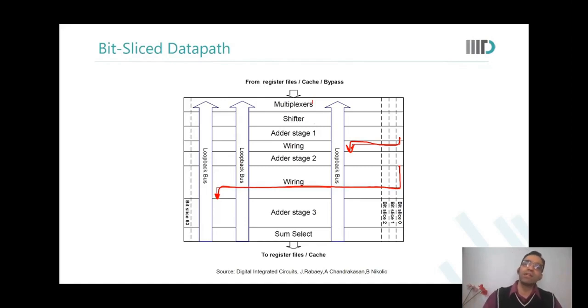So need not be. We're not saying they are symmetrical. What we are saying is data path is in one flow. This is just to streamline so that when you design, you do not end up with errors because of some confusion or interconnects. Because when we will see, just a little while later, tree adders, you will see there are such complex interconnects that it's better to separate it like this. Okay, sir.